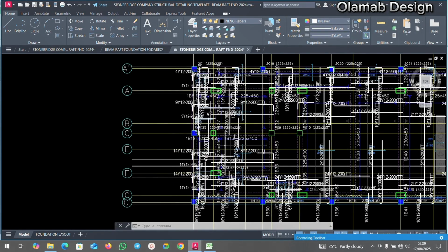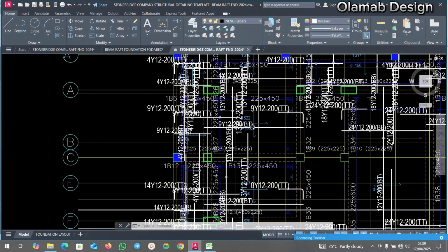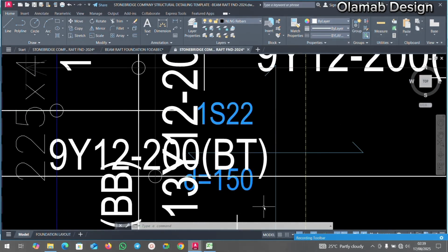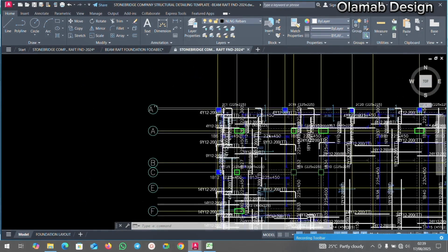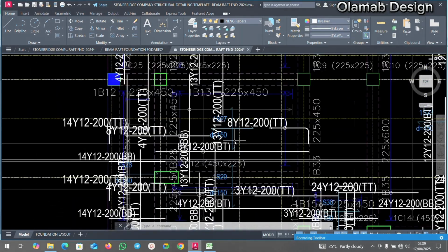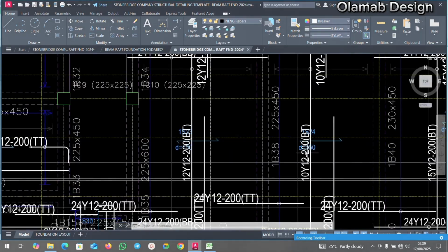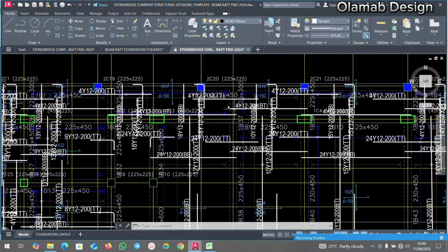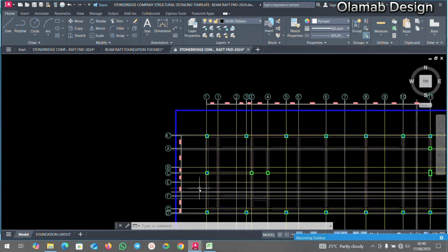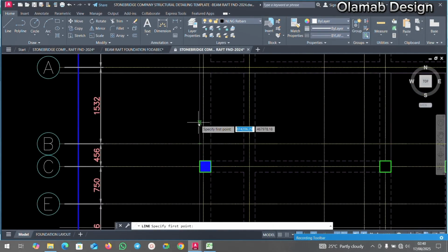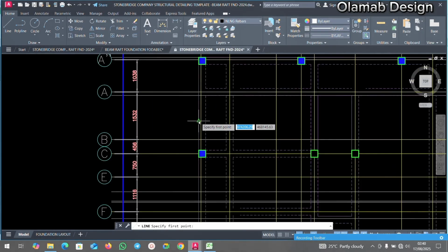If you check your original outcome from the proto structure, you can see that this is a two-way slab. It means that the reinforcement is going to run in both directions. Can you see it here? It is a two-way slab. Then this is also a two-way slab. This is a one-way. But irrespective of that, the right thing is you take your reinforcement, your rebars, this way.